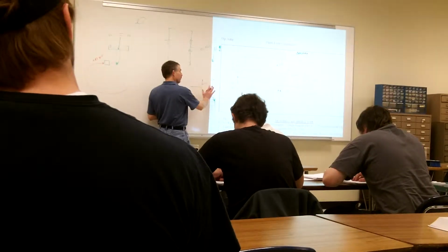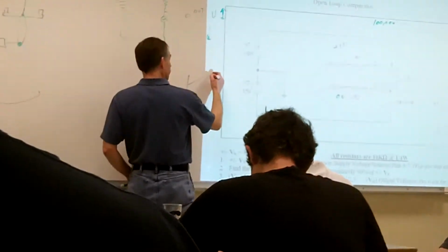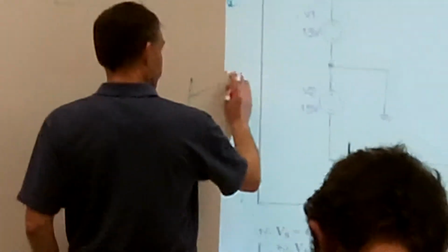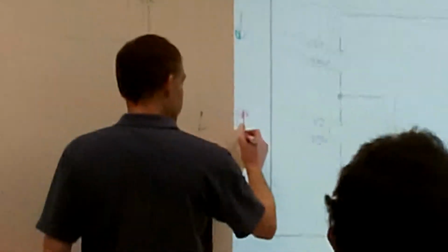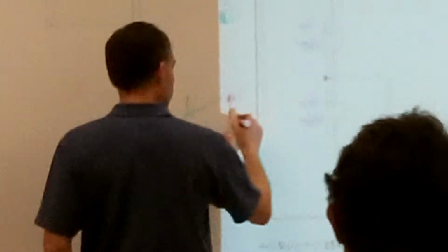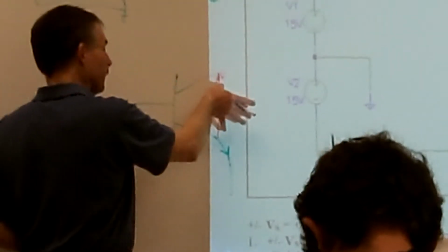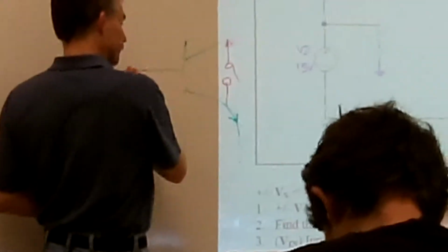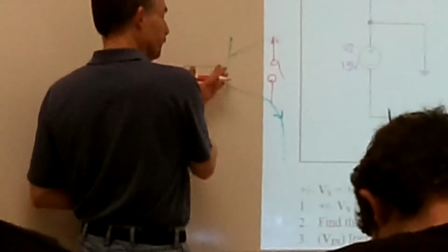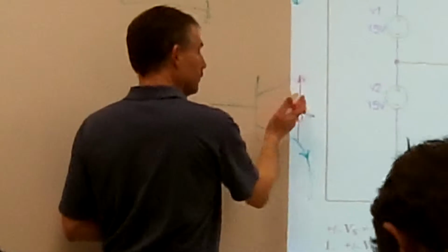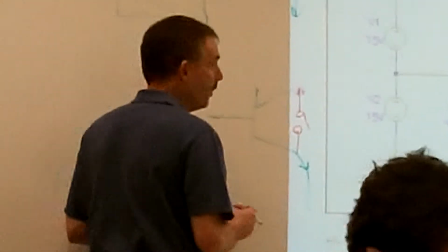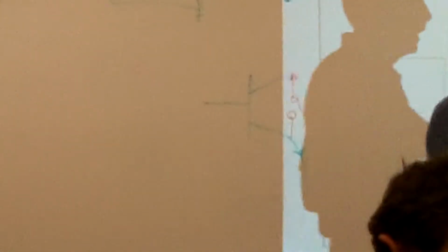These things, we're using them as switches. Remember, from our collector to our emitter, we could just treat these things as switches. So if we wanted to analyze how our circuit was working, we just treated them as switches. If the switch was turned off, the switch was open. If the switch was on, we had a voltage on our base, then the switch closed, and then our current started to flow. Well, that's kind of the same way we can look at the op amps too.